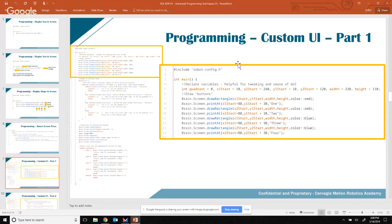So even if you have totally different autonomous routines, whenever the competition switches over to driver control, you have to put that code inside of every single program if you do this through separate programs. And if you make a change to one, you have to go back and update all 8 of those if you have 8 separate programs.